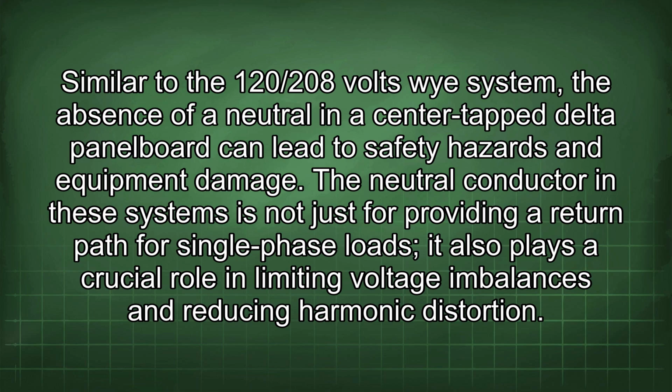Similar to the 120/208 volt Y system, the absence of a neutral in a center tap delta panel board can lead to safety hazards and equipment damage. The neutral conductor in these systems is not just for providing a return path for single-phase loads, it also plays a crucial role in limiting voltage imbalances and reducing harmonic distortion.